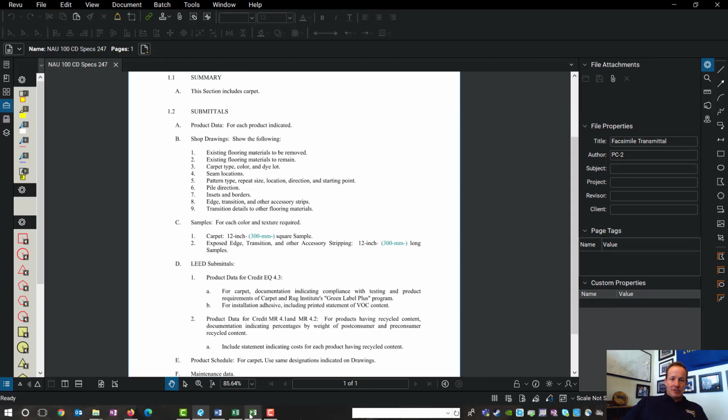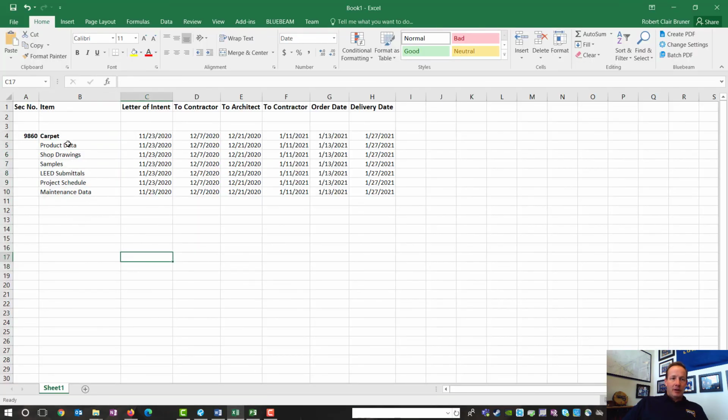And so that's what's going to be in my list. So in your assignment, each and every material in the restroom is going to have different submittals. Some are going to have shop drawings, some won't. Some will have lead submittals, or some will have samples and some won't.